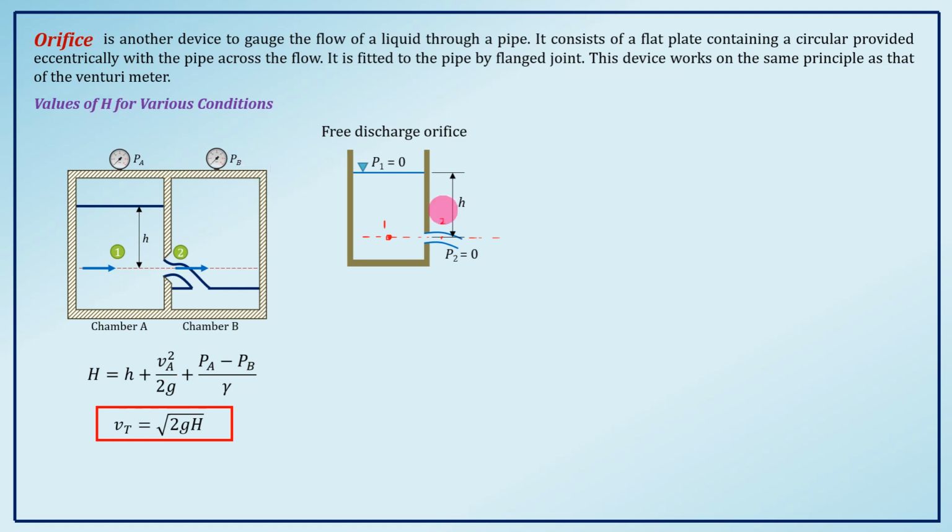Ayan. So, in this problem or in this figure, we have an open tank. Open tank, yan. So, kapag open tank, yung pressure natin at the top is 0. So, kasi gauge pressure. So, 0 yan. So, meaning, yung P1 na yan is yung pA, diba? So, kung 0 yung P1, 0 yan.